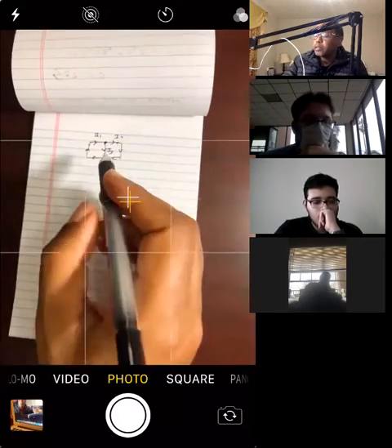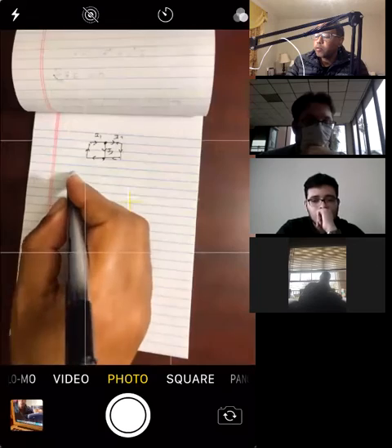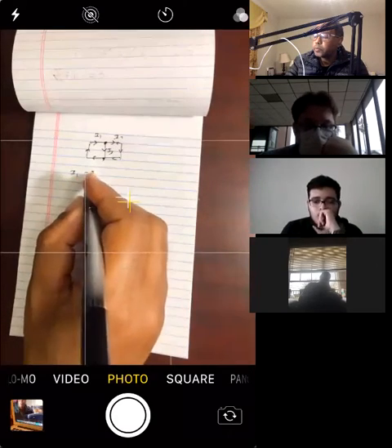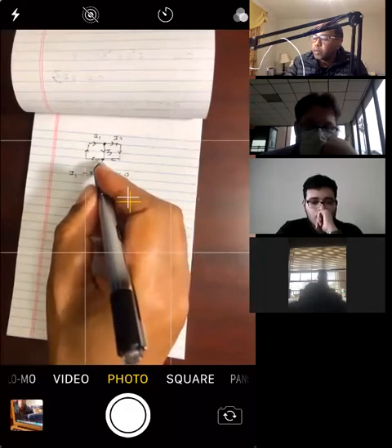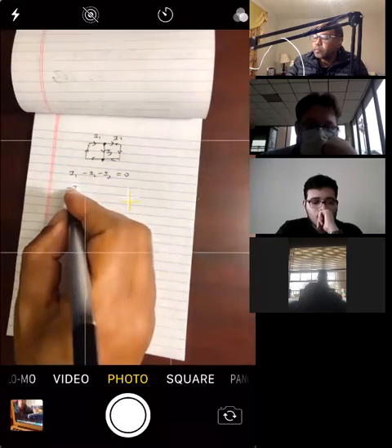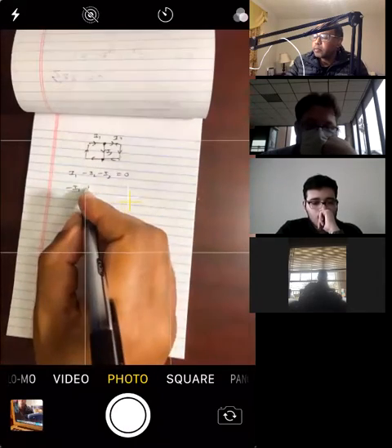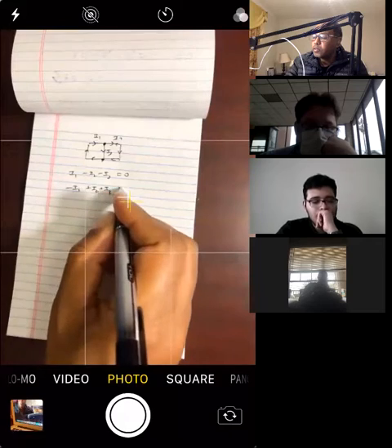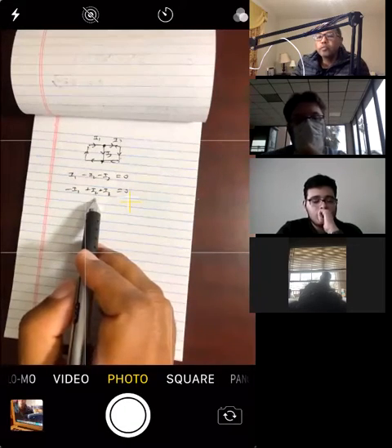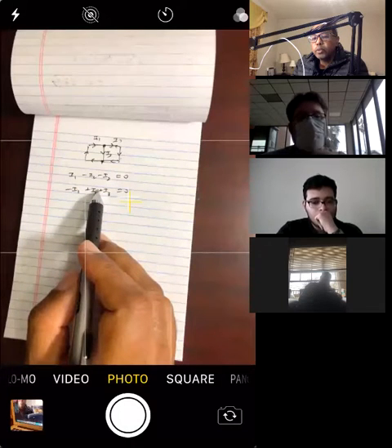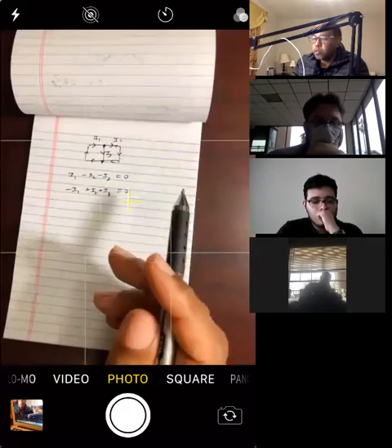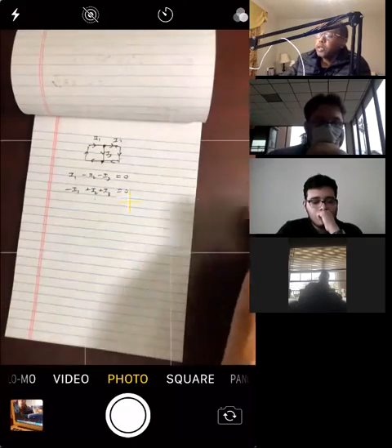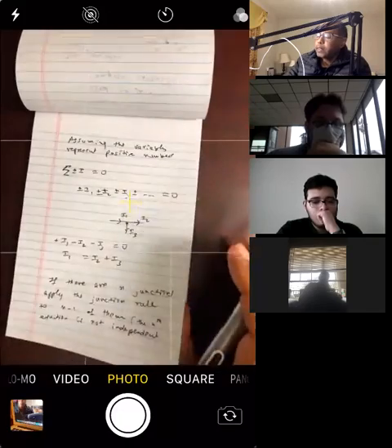So let's apply the junction rule over here. What do we get? We get I1 minus I2 minus I3 equals 0. Now let's use this other junction. Now you see I1 is coming out, so that's negative, but I2 and I3 are coming in. All it did was multiply this equation by a negative. It's an identical equation, not an independent equation. So if you apply the junction rule to all of them, the last one is going to be a dependent equation. If you have n junctions, you just apply it to n minus one of the junctions. So that's the junction rule.